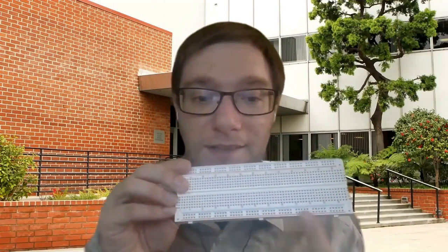The breadboard is itself labeled, where every hole has a row label and a column label. They go from 1 to 60 along the columns, and from A to J going up along the rows. Orient this breadboard the same way on your desk as in the PowerPoint presentation, with the numbers going 1 to 60 left to right, and the letters going A to J from bottom to top. That will help make sure that you're not putting together a circuit upside down from the way you're looking at it on the screen.